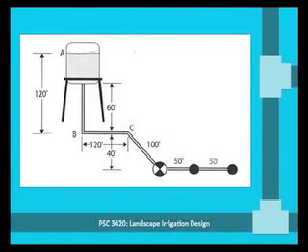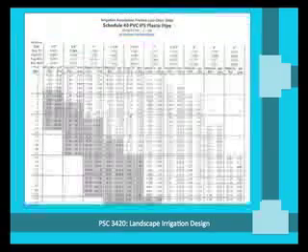The valve is open, that's how we're determining dynamic pressure, and the sprinklers are operating with a total flow of 30 gallons per minute. All the pipe between the tank and the valve is 1.5 inch Schedule 40 PVC, so what would the dynamic pressure be at the valve? We're going to ignore the tank and any fittings for this particular example, just for now.